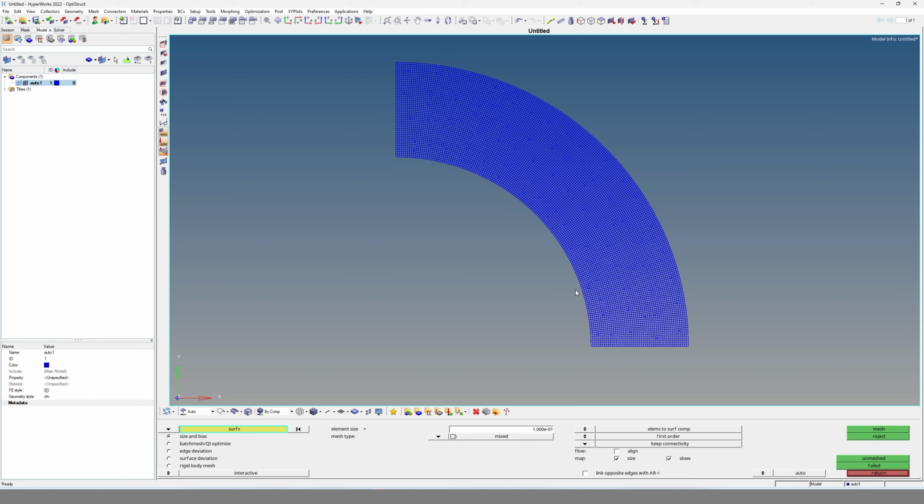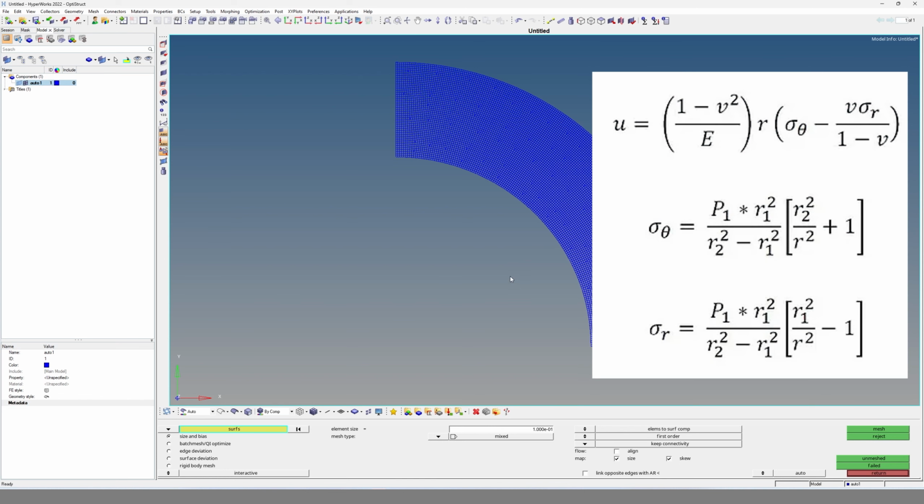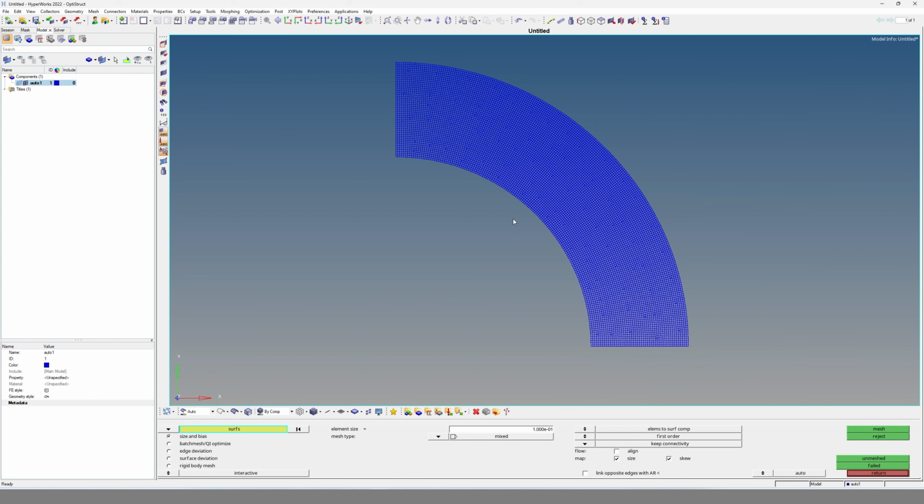As you will notice, in this case the material is irrelevant because, as you can see from the formula shown at the start of the video, the circumferential and radial stresses are independent of the material. So whatever material you use, it will yield the same result. The difference that a different material makes is that the displacement is different. It's dependent on the properties of the material.